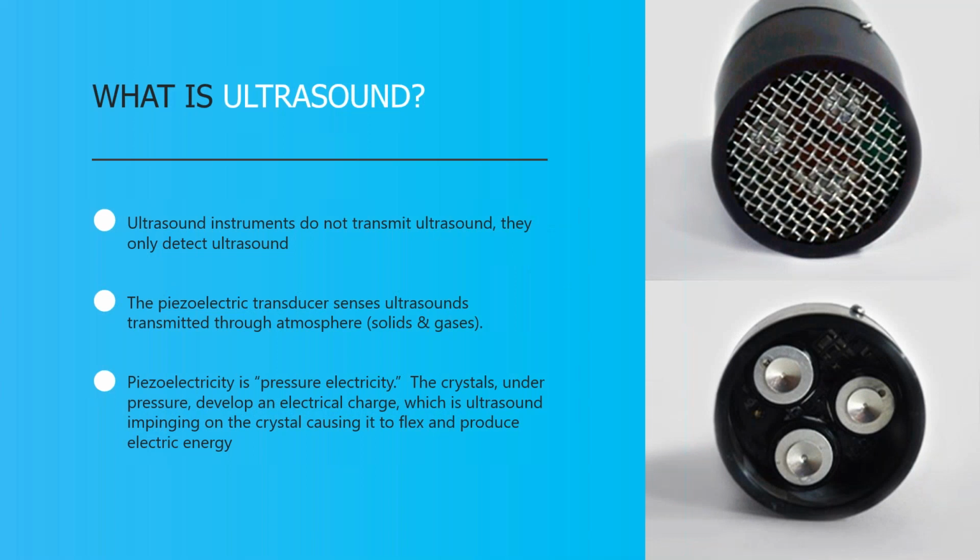So again, we don't emit sound, but we receive, and we're listening for high-frequency sound. The picture you're seeing over here on the right is our SCM, or the scanning module. It should look familiar to you, especially if you're using an UltraProbe 2000, a 9, a 10, or a 15. Those scanning modules will look identical to that one. What you see inside of there, in this case, is an array of 3 of the piezoelectric crystals. Those are what actually sense and receive the high-frequency sound. And when those crystals sense that high-frequency sound, they flex and bend, and that produces electrical energy.